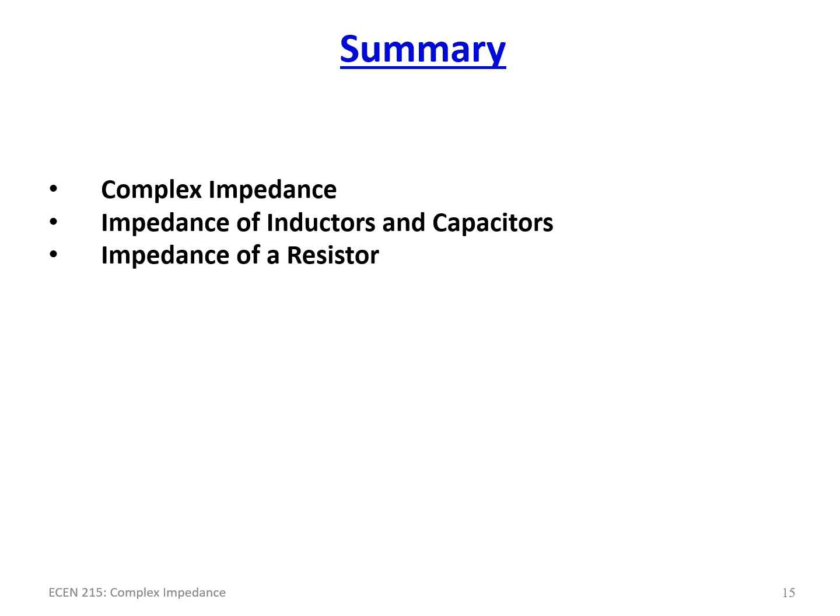So we have the impedance of the resistor, obviously R is equal to R. And then we talked about equivalent impedance. Similar to resistances, impedance and resistance are kind of hand in hand, the same, especially when we're about to come into circuit analysis in the AC domain. Everything works exactly the same. You add series impedances together, and in parallel impedances, you apply the reciprocal. So you have 1 over R1 plus 1 over R2 plus 1 over R3,